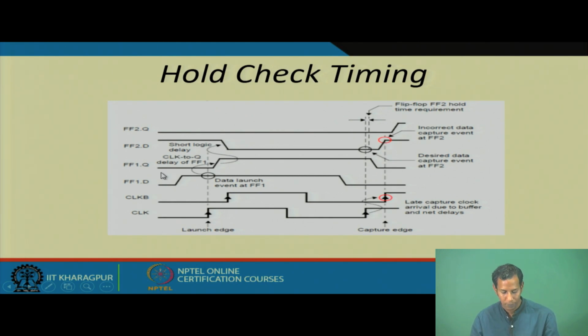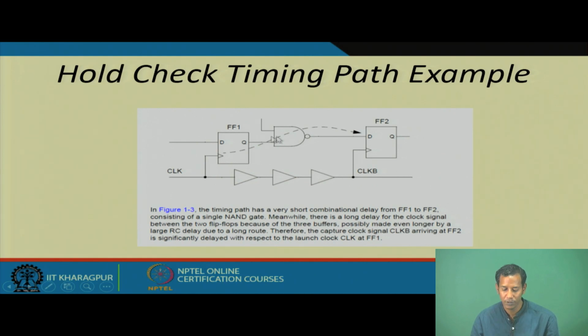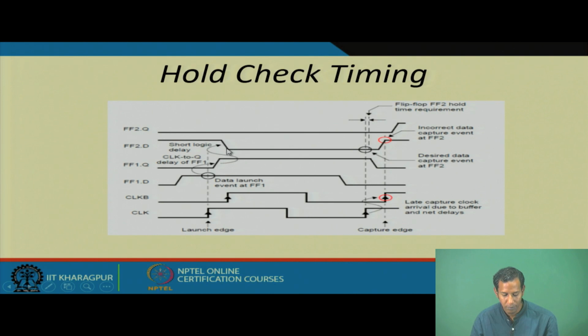Why? Because it depends upon flip flop 1, and this Q has to pass through this NAND gate and then again reach flip flop D. So, if you consider flip flop D, it will have the corresponding output of the NAND gate, and there is a very short difference because of the delay of this particular NAND gate. After that, it works like this again.